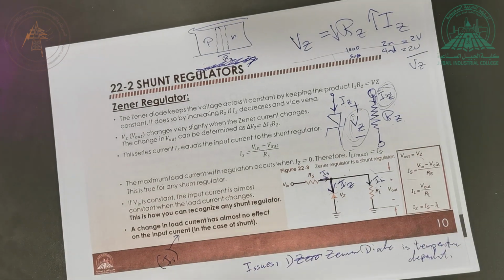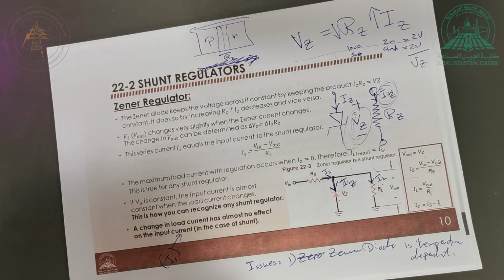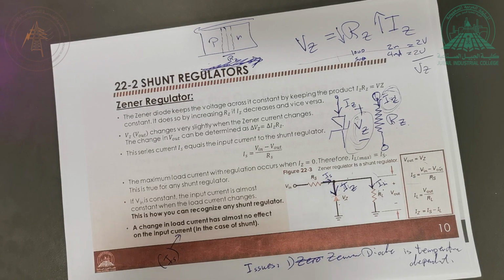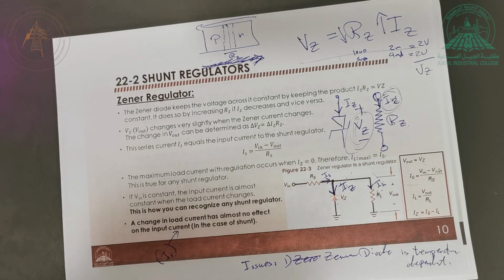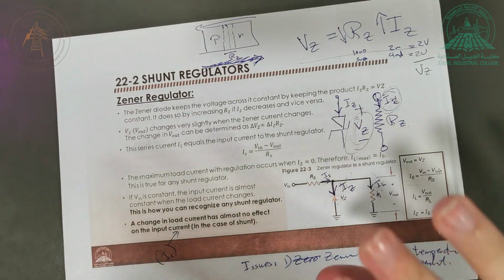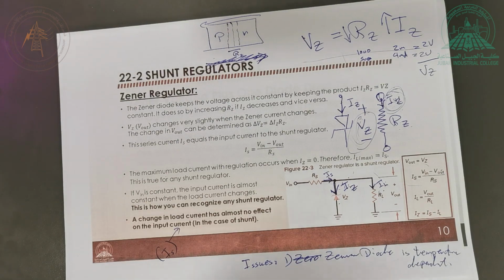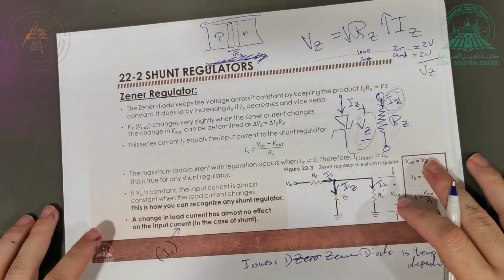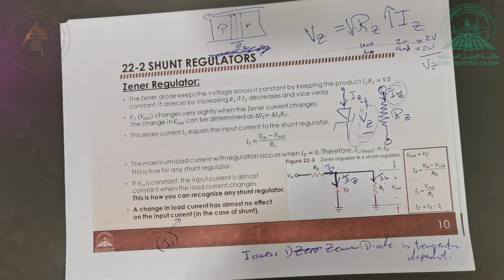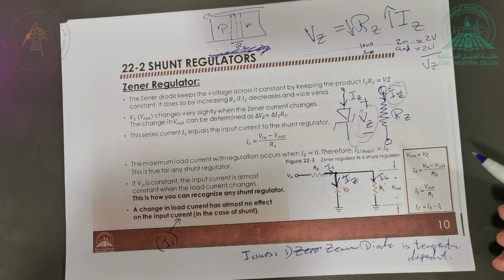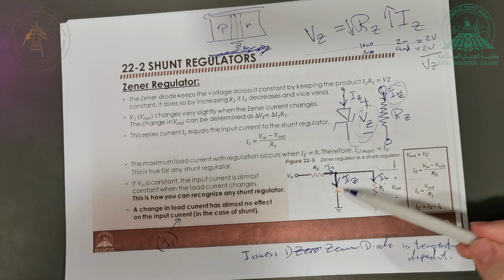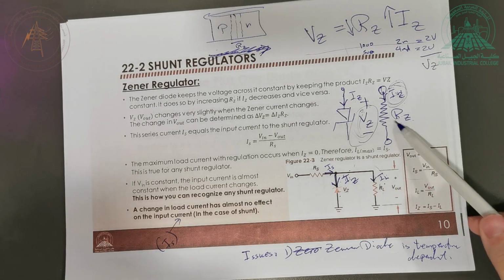Right? What does it mean? It means that when the device heats up, which is expected and typical in the case of power regulators, this value of Vz changes a little bit. Why? Because RZ itself changes. Remember, resistance usually changes a little bit with temperature. So the Zener diode, or actually any diode, has characteristics that are sensitive to temperature. And this sensitivity becomes worse the bigger the Vz becomes, since RZ will become more.